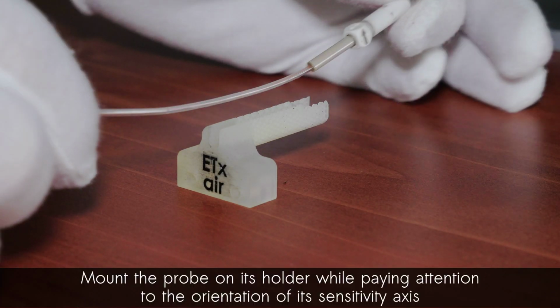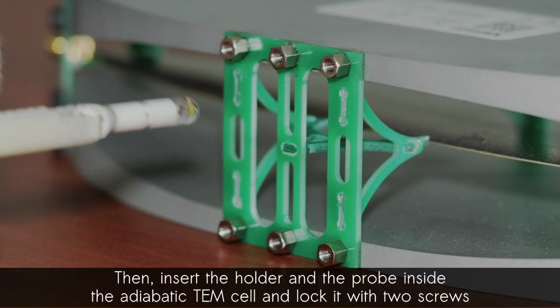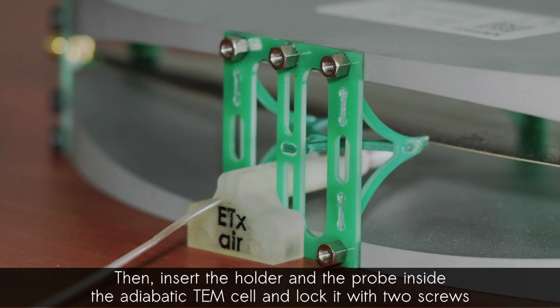Mount the probe on its holder while paying attention to the orientation of its sensitivity axis. Then, insert the holder and the probe inside the adiabatic TEM cell and lock it with 2 screws.